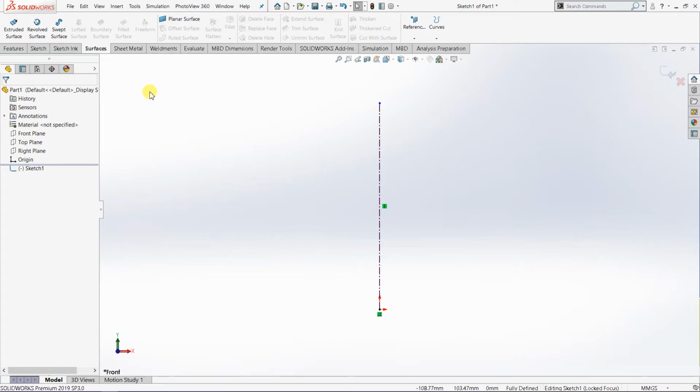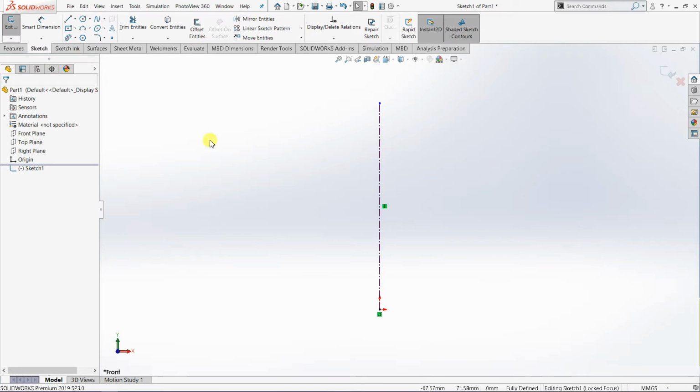As I mentioned previously, under the 3D surface, you can use a sketch that is either a closed loop or an open loop. In this case, I would like to show you how to apply the closed loop. Let's say I'm going to apply the 3-point arc slot.